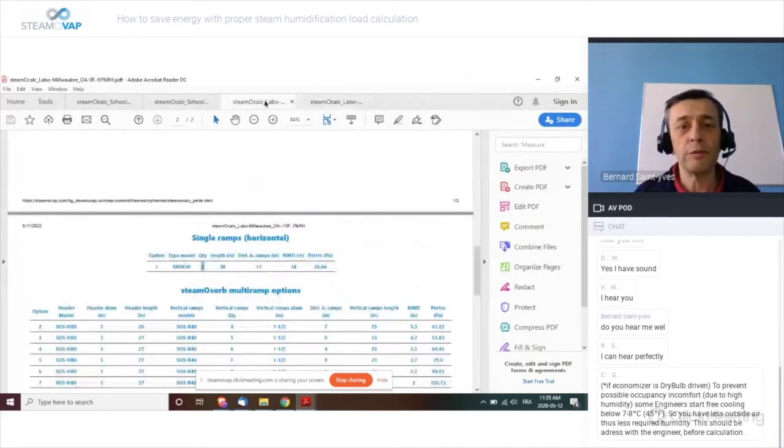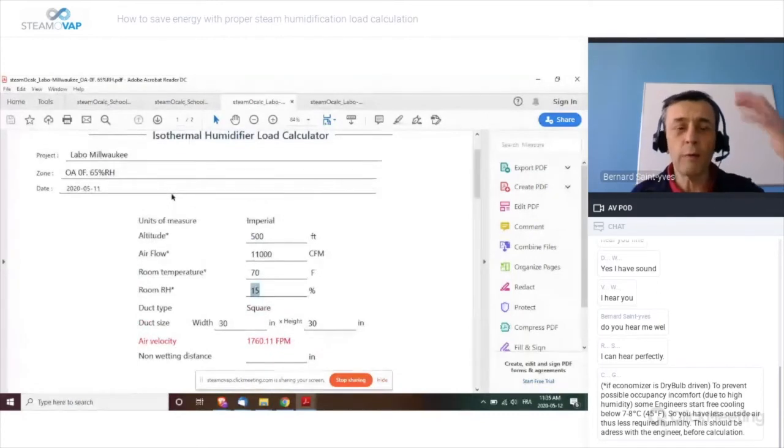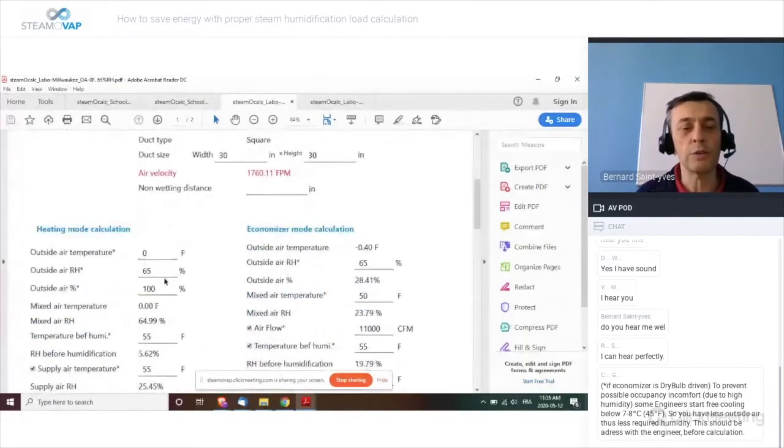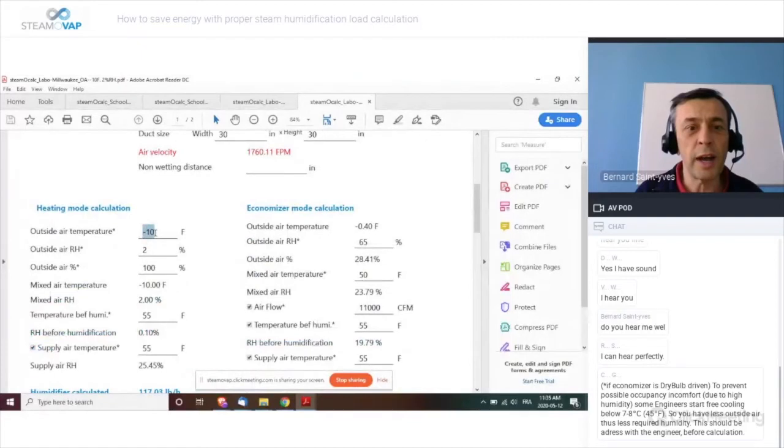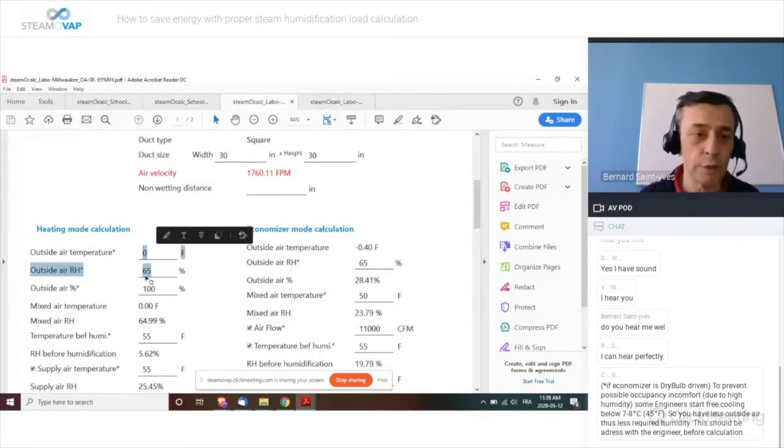Okay. And then if you go back to the question I was asking myself, why did he consider so little humidity in Milwaukee for the outside air? I know that most of you will think, oh, Bernard, at this temperature, it doesn't make any difference. Yes, but you see, minus 10 Fahrenheit, even in Montreal, we don't take this low temperature. So I considered as outside, based on the information I found on the web, 0 Fahrenheit for Milwaukee, and around 50 to 60 or 70% relative humidity for the outside air.